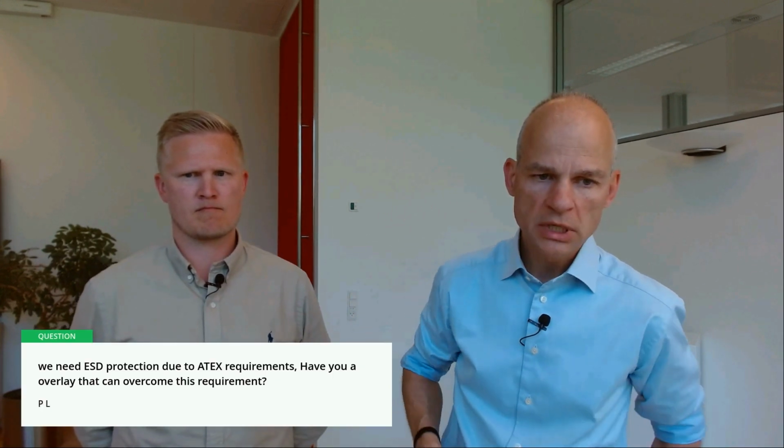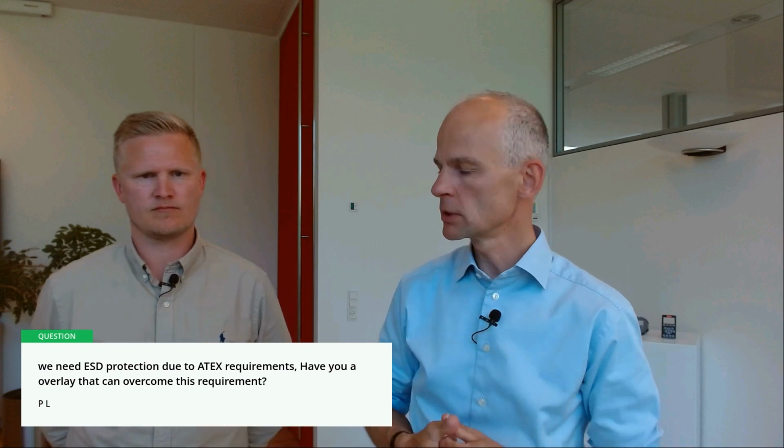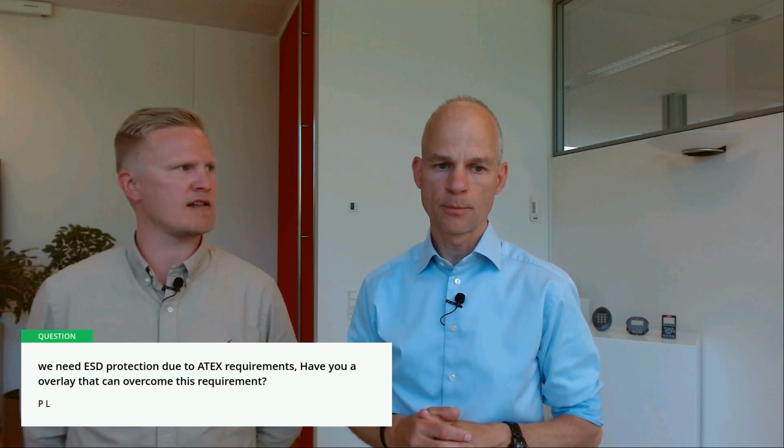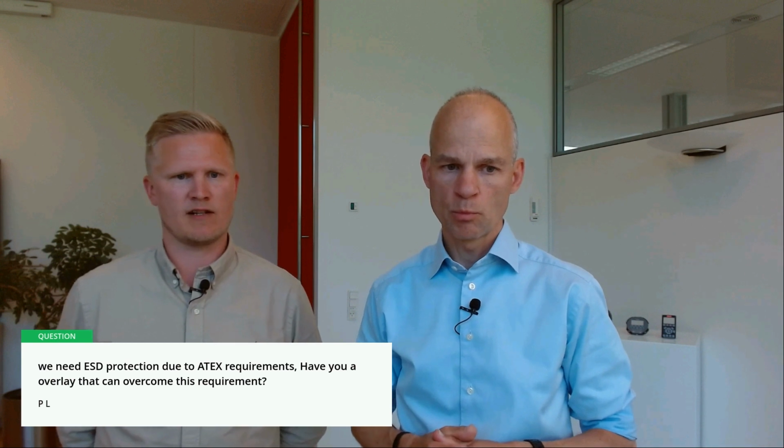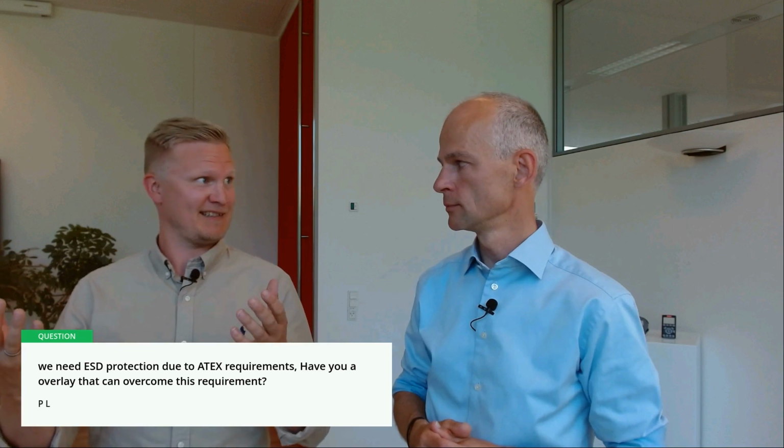So another question here from Peter. We need ESD protection due to ATEX requirements. Do you have an overlay that can overcome this requirement, Thomas? Yeah, definitely. We are very familiar with this requirement, especially within the oil and gas industry, where it's a critical safety feature for the top layer of the overlay to be anti-static, so that it doesn't, in the worst case, create a spark, and that's not good if you're in an environment with gas.